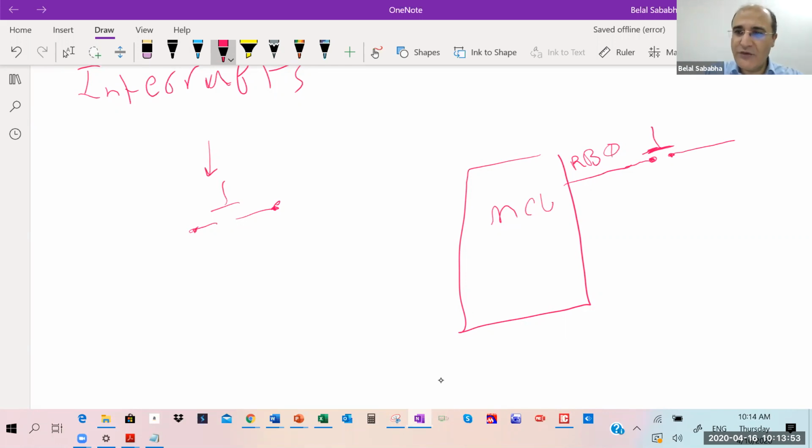Right now, you saw the jumper. There are 3 pins here, 1, 2, 3, right? This is connected to VCC, and this is connected to ground. This is the jumper I showed you. Last time, these two were shorted together. When we started our program, the button was not pressed. So this was floating. The voltage level here is connected neither to ground nor to high, so it was floating, so unexpected things can happen.